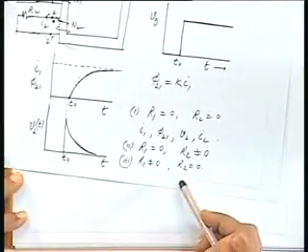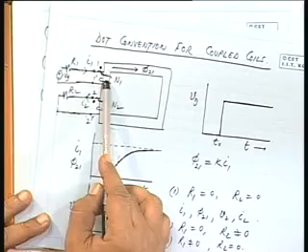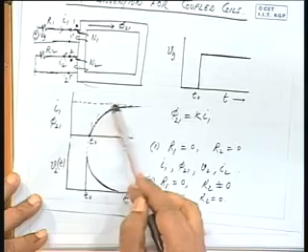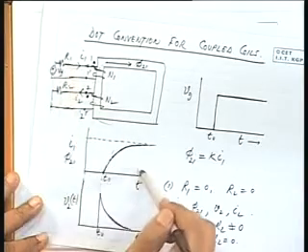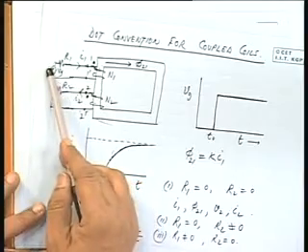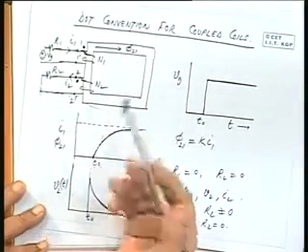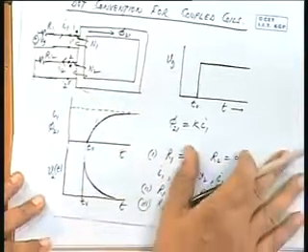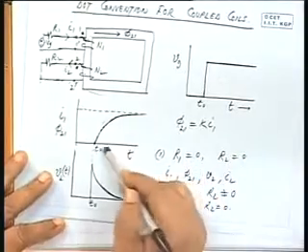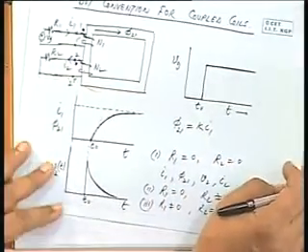So this is a situation when the secondary side is open. If you apply a DC, it is a simple RL circuit. So after some time the current will come to a steady value like this. This current is decided totally by the resistance and the voltage supplied. So voltage by resistance will be the current. If you apply a very large value of voltage, say 220 volts DC, and the resistance value is small, then it will damage the winding, it will burn out. So the chances of the winding getting damaged will be controlled only by the resistance value, which is normally very low.